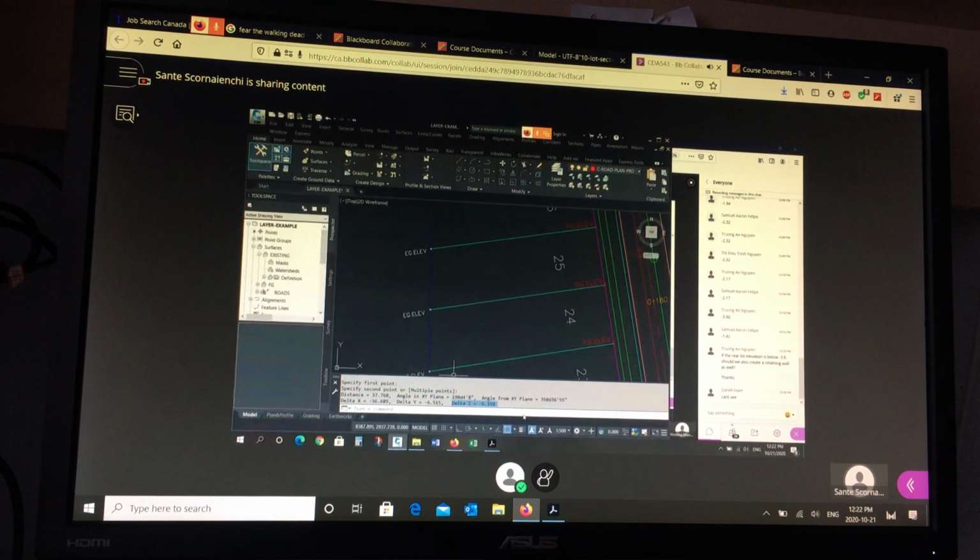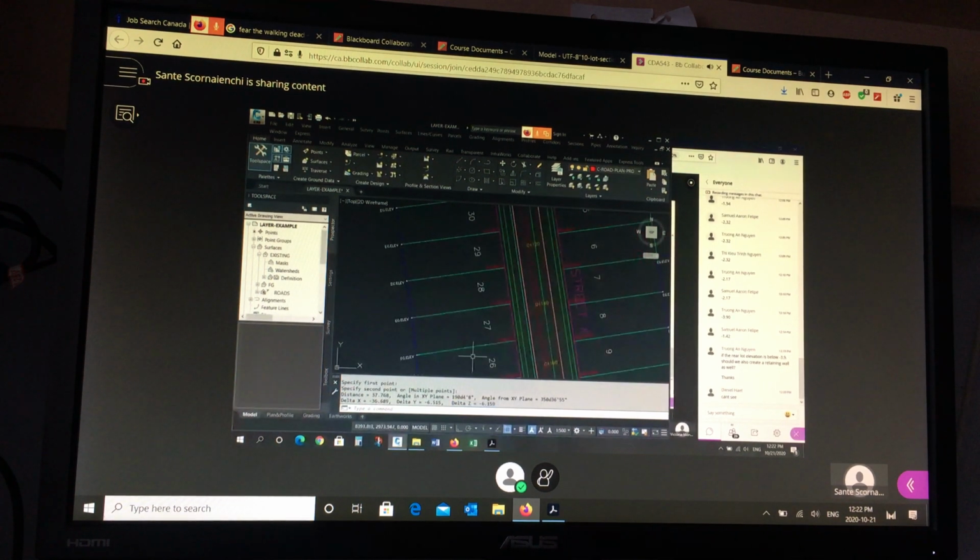So what am I going to design? A full walkout with a minimum backyard, and there's still going to be a wall at the end, a couple of meters high. Everybody understand what I just said and why I said it? So you have to design each one. Then I'm going to go to the next one. So I'm going to design this one. I'll input all those numbers. Every time there's a change in slope, I need an elevation.